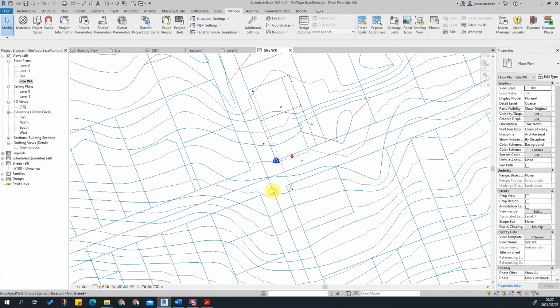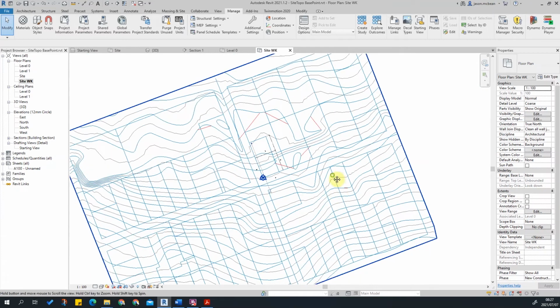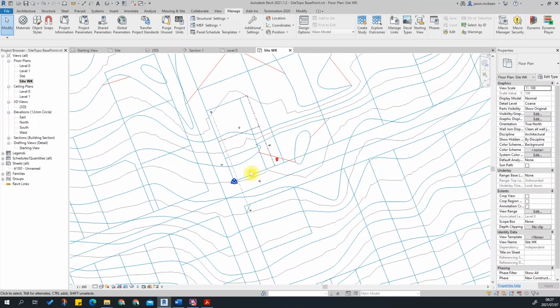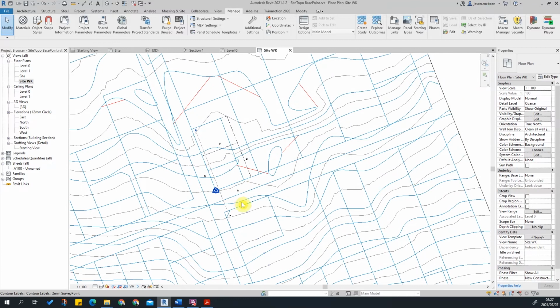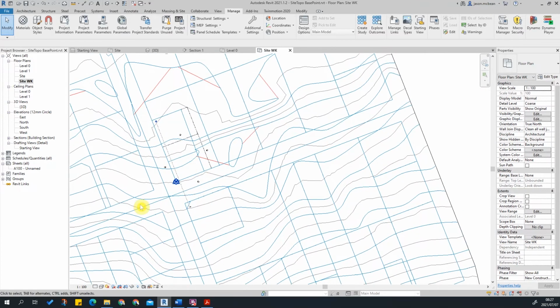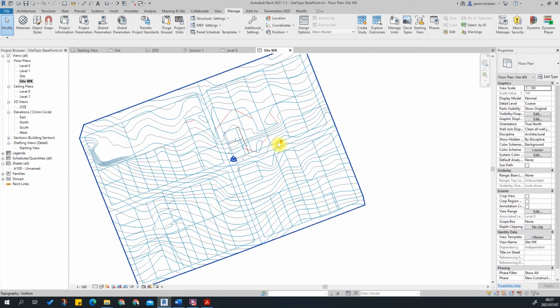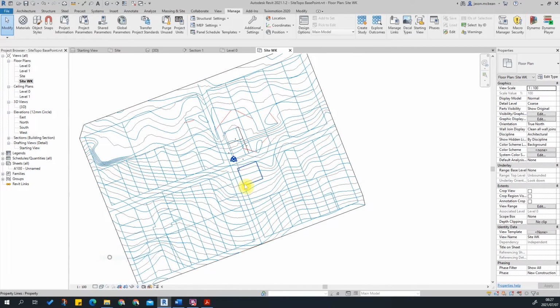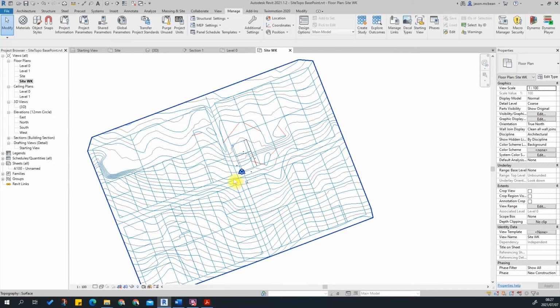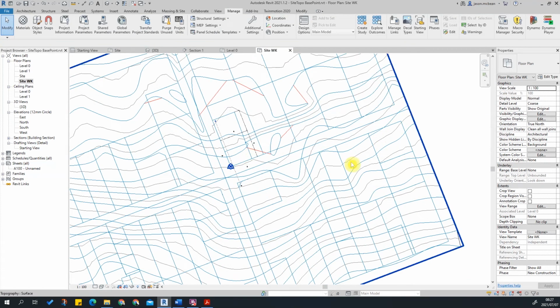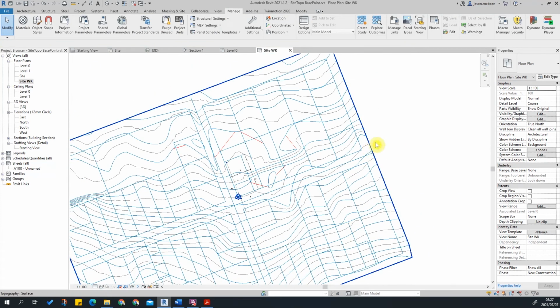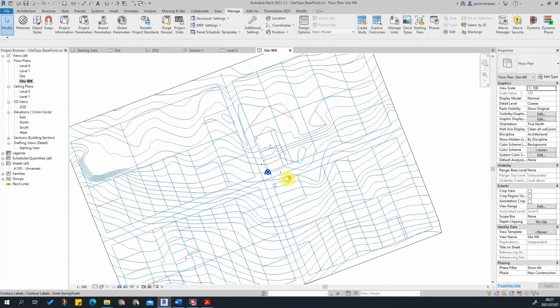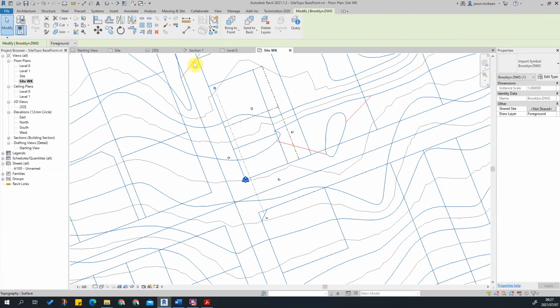Because what I'm looking for is the road center lines, etc. Okay. Right, now that I've started to establish this information, I need to bring in some aerial photographs to start using that as well. In this case, I might switch to wireframe because the image will sit below everything. You don't want the image above everything else. The DWG file is fine over everything else, but the aerial photograph I want to bring in and also put underneath all this information. So the first thing I do with the AutoCAD file, once it's in, is pin it.